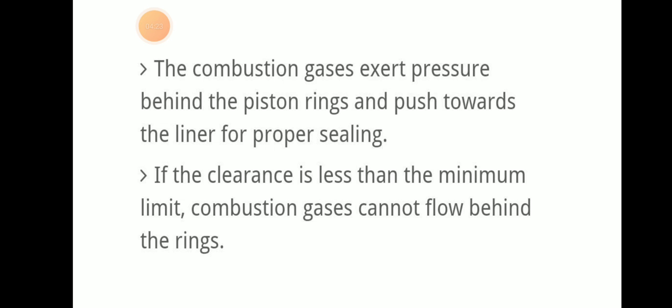The combustion gas exerts pressure behind the piston ring and pushes it towards the liner for proper sealing. If the clearance is less than the minimum limit, then combustion gas cannot flow behind the ring. So proper combustion will not happen.